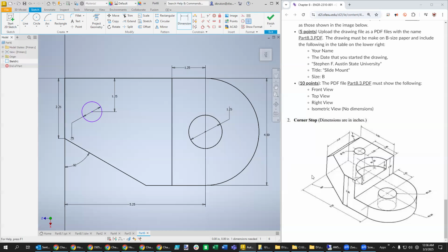And because they didn't really give this as 4, I am going to delete this one just to try something out because it should take us away to, we hit Control Z for a second. Oh, there's one dimension missing still. Oh, that's the placement of this guy. All right. So let me go ahead and delete that 4 like I was doing. Because really over here, they give us the radius of this arc. So let's just change that up to be more like what we have. And you can see that it's going to be exactly 2. And now we're back to fully constrained, except for the one distance, and that is the distance from here to over here. And it said that that was going to be exactly 2.